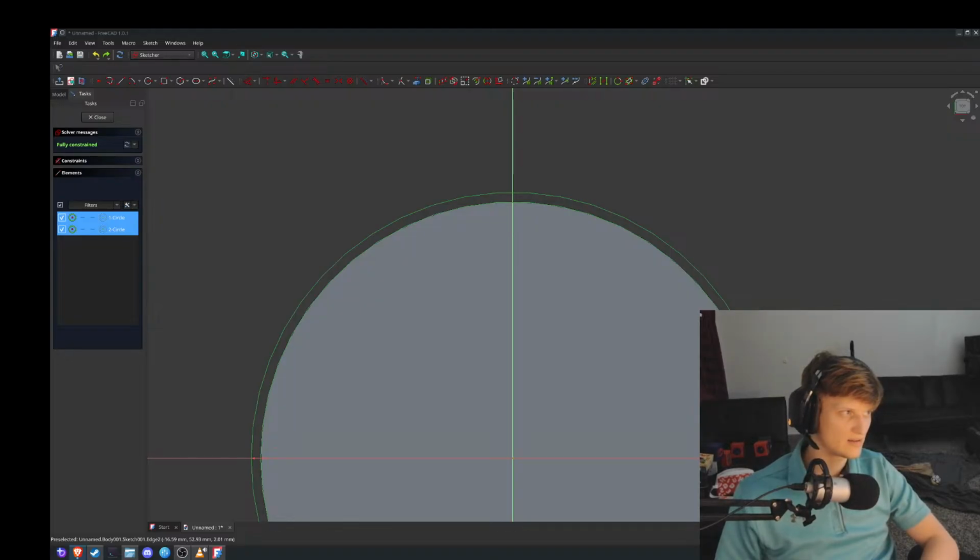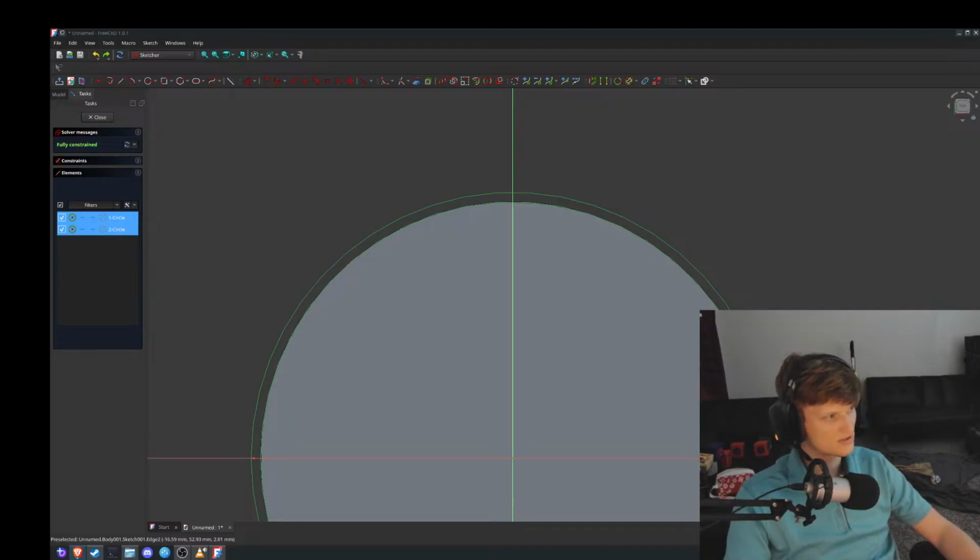FreeCAD. How to extrude the space between two sketch circles. So simple of an action. To extrude the space between two circles, you need to ensure the geometry is properly set up in the way that FreeCAD recognizes as a closed shape. There's a general approach. Create a sketch with two circles.